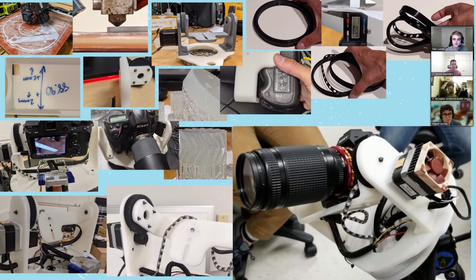Those actually didn't end up working out very well because resin tends to be brittle. So we ended up actually using something called TPU, and TPU has a little bit of give. So that actually came in handy when it came to printing the gears, but not just the gears. Also on the right there, you can see these 3D printed bearing assembly pieces. So a bearing is a very, very important part of making this thing work, but it was very difficult to come up with something that would work out and not be brittle. So using this TPU actually ended up being just fine.